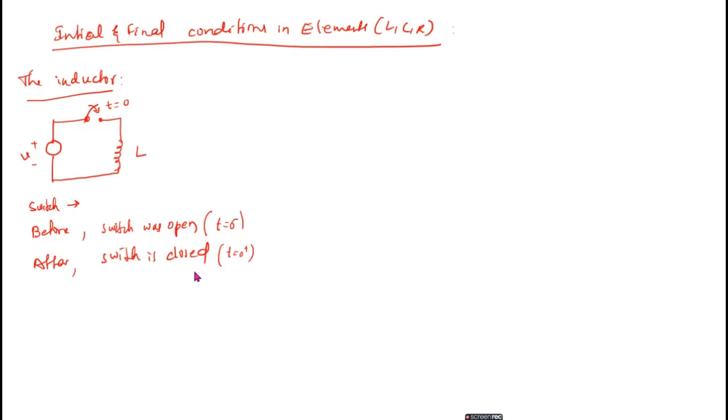Okay, we know the expression for voltage in an inductor. Voltage across the inductor is equal to L into dIL by dt. Call this equation number 1. It is a standard formula. Voltage across an inductor is given by L into the differentiation of the current flowing through it. And always L is measured in Henry, voltage in volts, and current in amperes.